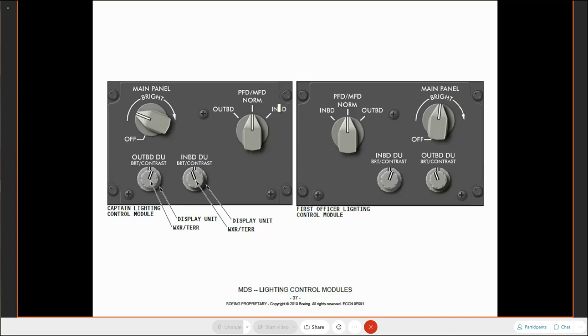When I mean compact, if the captain had a full nav display on their multifunction display, then it would go into a narrow format, a compact mode. So the nav display would shrink to half the screen size, and the other half would then become the primary flight display. So we've maintained the visibility of the PFD for the captain. Okay, PFDs, primary flight displays, are essentially more important than a nav display. You don't always need a nav display, but you do need a primary flight display.